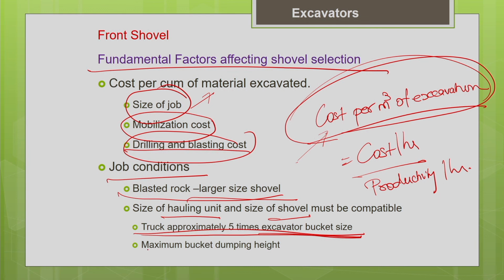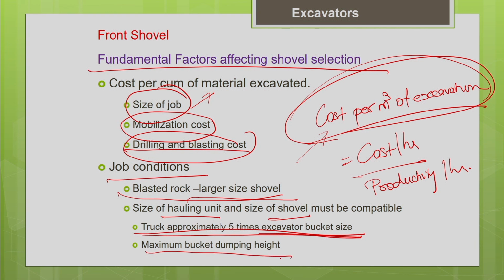And you should also select the machine, the shovel dimensions in such a way that it will be able to reach your truck. That is why the maximum bucket dumping height is also very important when you select your truck and the shovel. All these basic guidelines you should keep in mind when you select the shovel for the particular job.